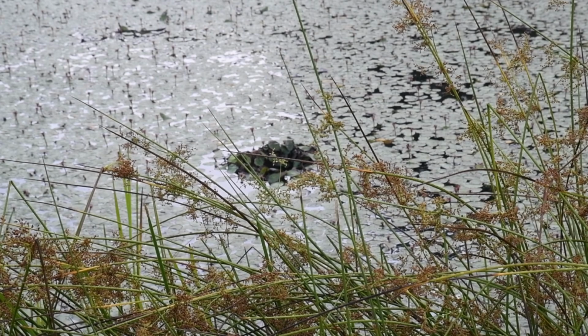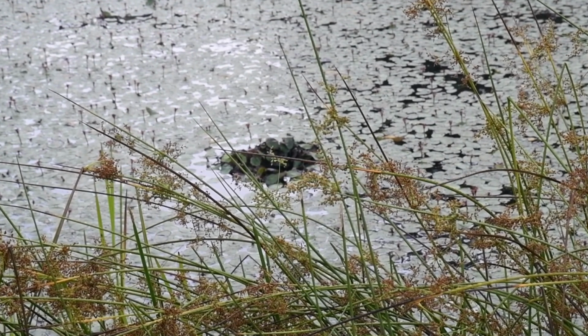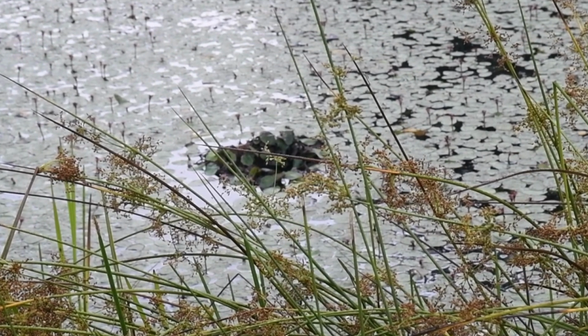It's a vertical pipe, and it connects to a drain pipe and it carries water underneath the dam without causing damage to the dam. It looks like it's functioning properly. However, the aquatic plant water shield is partially blocking the entrance to the pipe, and it will only get worse. It could block the entrance to the pipe, so we better clean that out so the pipe works as planned.